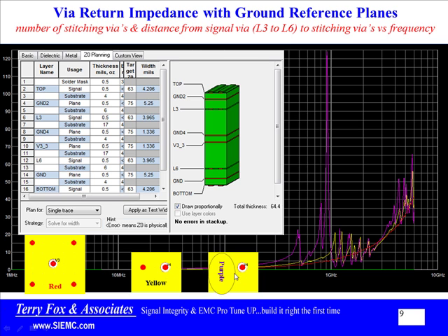So in other words, here's the via, but I don't have any stitching via tying ground to ground anywhere close to this, and so consequently there's a frequency response curve to it, and that is this purple line. By the way, the tool that I'm using here is Mentor's HyperLynx Power Integrity, and I'm using LineSim in this case, but very nice tool, very nice tool.